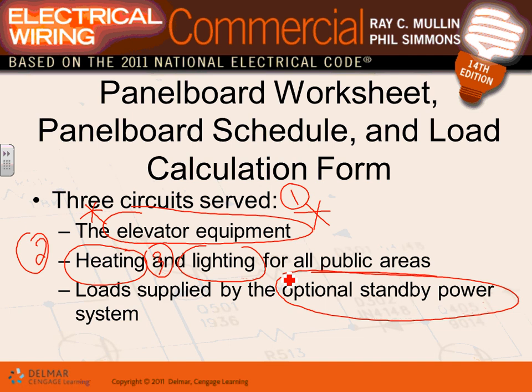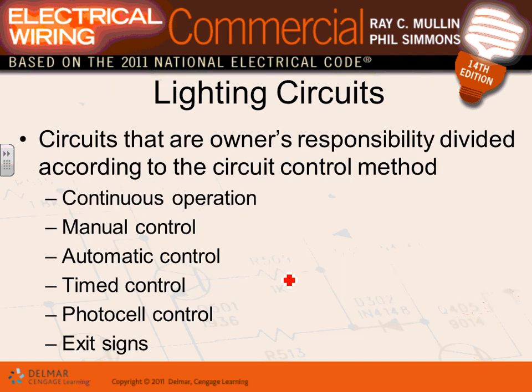loads, guys, on an optional standby power system, meaning a generator. If all these loads will be backed up by a generator, so upon the loss of power, the owner panel will be energized by a generator. I don't think they listed it as an emergency generator. It could be also listed, depending, if it comes within 10 seconds, it becomes an emergency generator. That's the only difference. And it's backing up the power in the common areas.